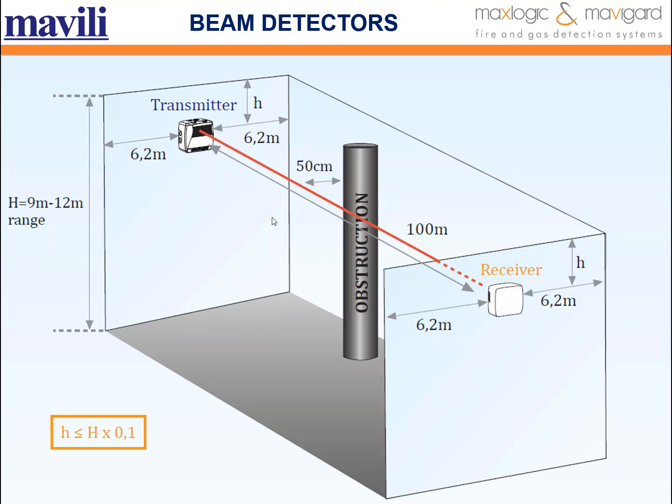Using beam detectors is appropriate in high ceiling areas like warehouses, hangars, atriums, and sport facilities that have high ceiling buildings. For beam detection, it is important to coordinate all fire protection measures and control their interactions accordingly. The requirements of this guide should only be taken as a starting point, and additional detection may be required in these places.